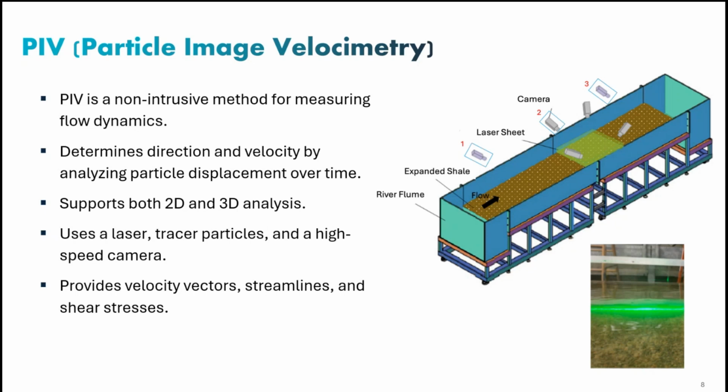You install several cameras if you want a 3D image of the fluid dynamics, or you can put one or two cameras to look at the 2D flow condition in the system. In our case, we installed one camera, but at 3 different locations: one close to the entrance, one in the middle of the channel, and one towards the end, to have a 2D side view of the flow in the soil.